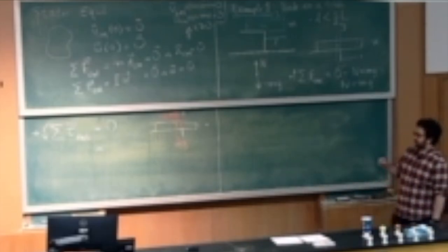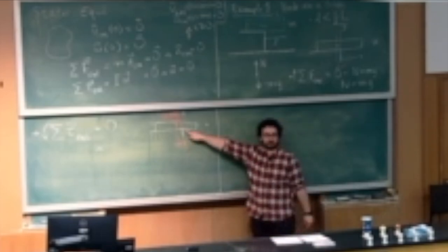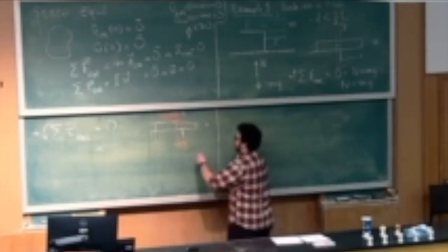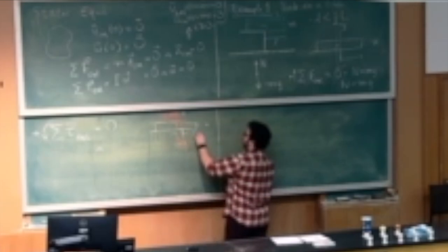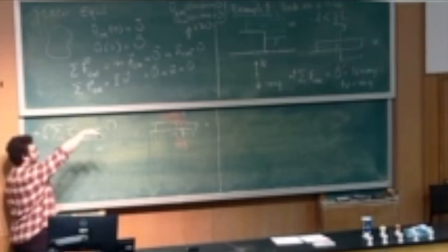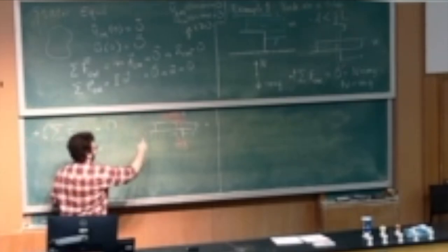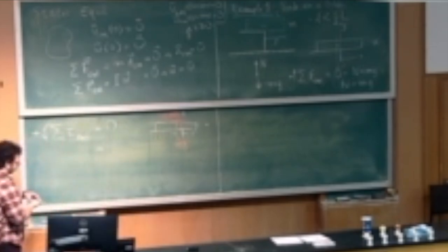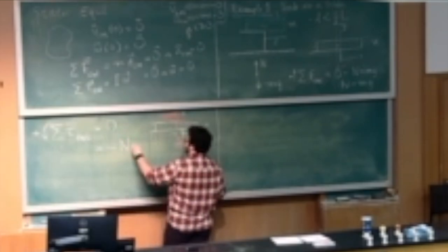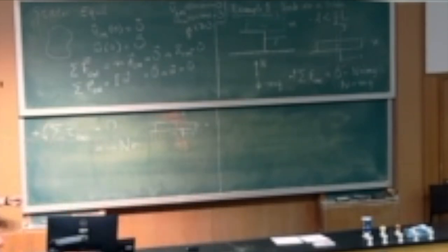Cool. Now let us write down all the torques about this pivot point. So this is our critical point, right? If there is, let's say, too much moment or torque about this point, this guy will tip over. So remember at this distance, this is R. Okay? So we have the normal force trying to create a torque in the clockwise direction about this pivot point. So since it is clockwise, it will come with a minus sign. So we have force times the moment arm or torque arm.